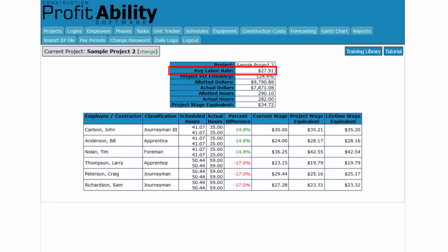So over the entire project from start to finish, this is the actual labor rate for your crews on site. It will fluctuate as workers of different wage levels enter and leave the project. It's a good number to keep an eye on, as you'll probably want to hover around the estimated average labor rate. While I've had success on projects running at an average labor rate higher than my estimated average labor rate, if you can get below your estimated average labor rate with a good crew, you can capture a little extra margin on each task. This report will tell you if you're achieving that.